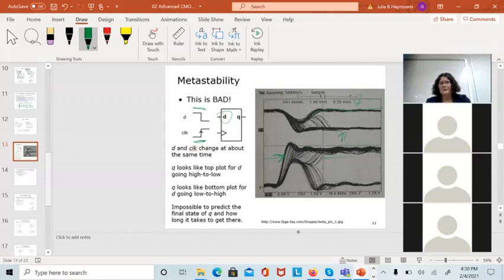So when you're trying to push a process, maybe the process was designed for a 10 megahertz clock and suddenly your boss wants you to take pictures twice as fast, so you're going to use a 20 megahertz clock, you have to stop and consider this. Sometimes it works and sometimes it doesn't, depending upon how much of a margin of safety you've added into that design.